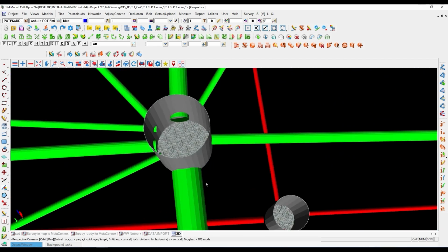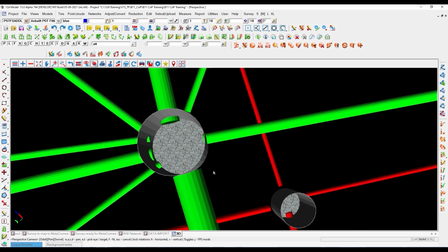One of those would be the fact that if we look at this chamber here, the pipes don't meet in the middle. That's based off the code of practice, which defines the center of the chamber as being the center of the steel lid, not the physical chamber. I know that these pipes actually met the side of the chamber as it met the manhole, but it's defined on the chamber.